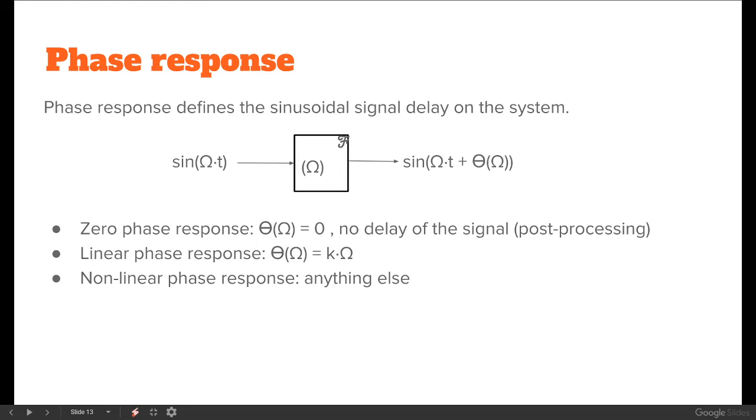That's a constant time shift for any frequency component. Meaning that if you have a signal with multiple frequencies, they will be delayed in the system by exactly the same time. Think of data transfer now. You probably want all of the frequency components which are coming in to come out simultaneously. Otherwise, you will start skewing the signal.